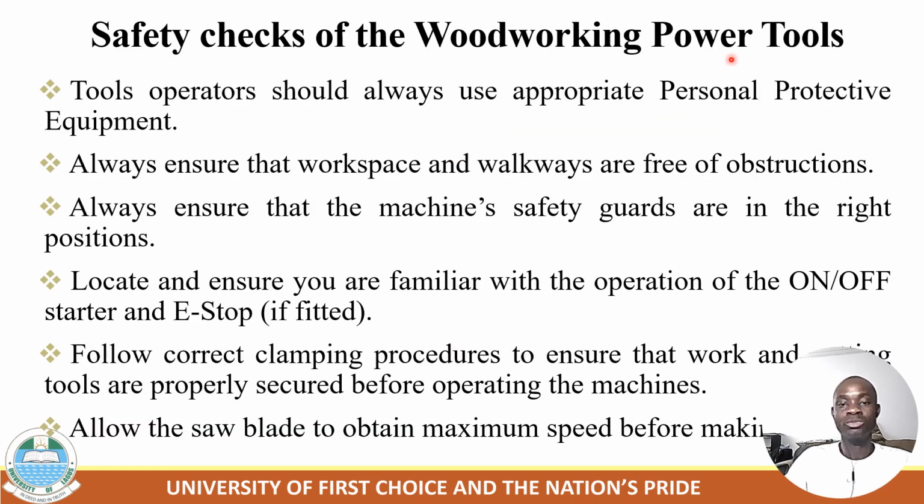Safety check on the woodworking power tools. Number 1, operators will always use appropriate personal protective equipment. Always ensure that workspace and workway are free of obstruction. Always ensure that the machine safety guards are in the right positions. Locate and ensure you are familiar with the operation of the on and off starter and e-stop.